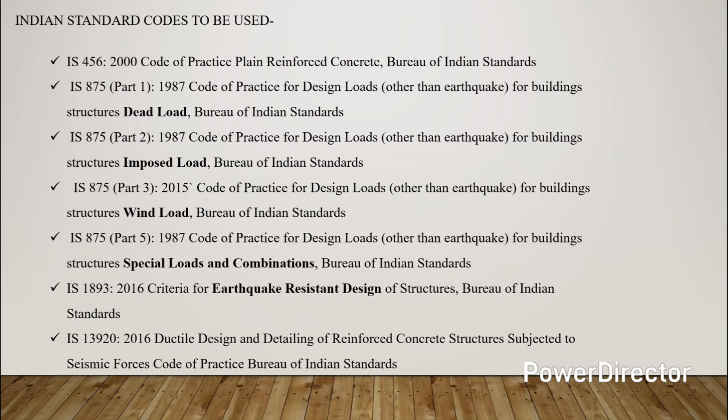See, we are not using IS 875 Part 4 because IS 875 Part 4 is for snow loads and we are not taking the location near the snow, so we are neglecting the code IS 875 Part 4.